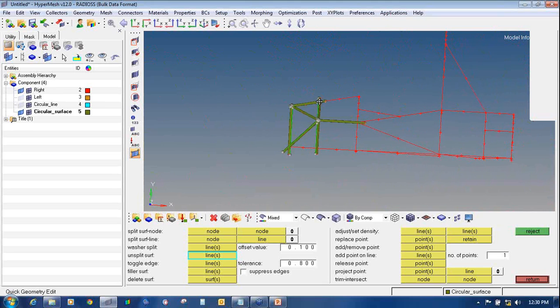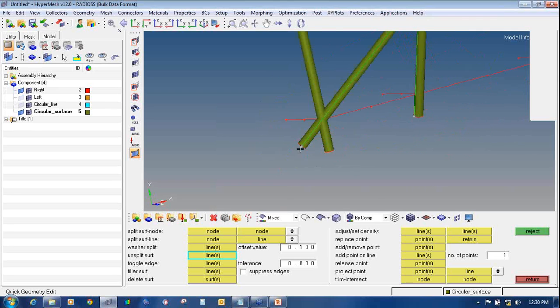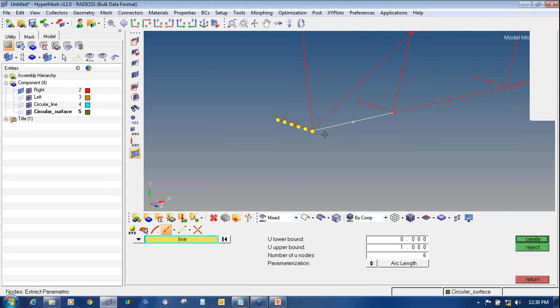In the same way you have to keep on doing all these for the top surfaces. So I will now show you how to create a square section and how to edit that square section. So I will off this, go to F8, create the nodes. On this particular roll cage structure, all my bottom beams are square sections. I will create the square section on the bottom beams. So I will show you how I will create that.